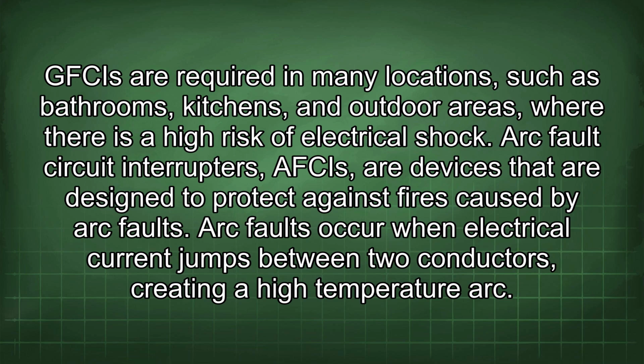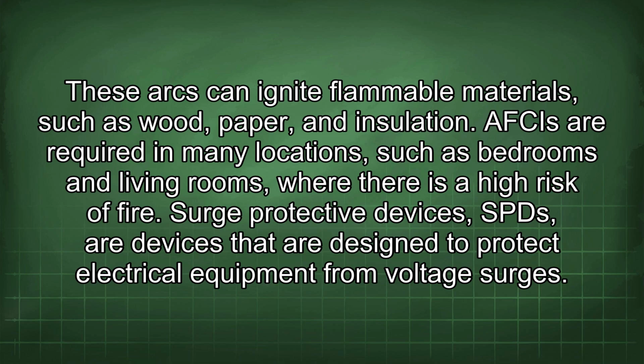Arc fault circuit interrupters, AFCIs, are devices that are designed to protect against fires caused by arc faults. Arc faults occur when electrical current jumps between two conductors, creating a high-temperature arc. These arcs can ignite flammable materials, such as wood, paper, and insulation. AFCIs are required in many locations, such as bedrooms and living rooms, where there is a high risk of fire.